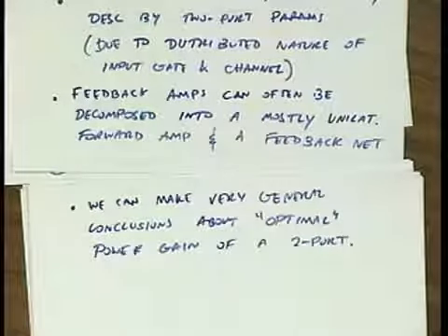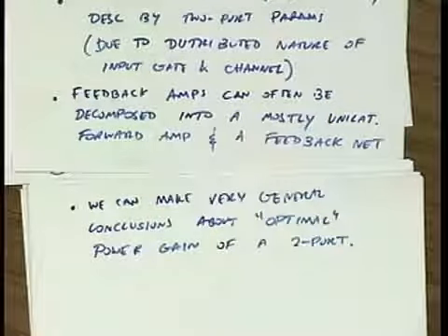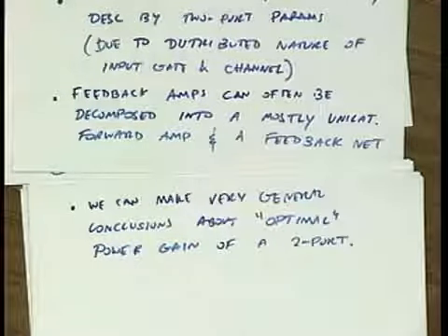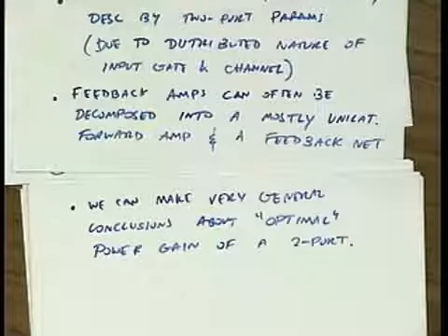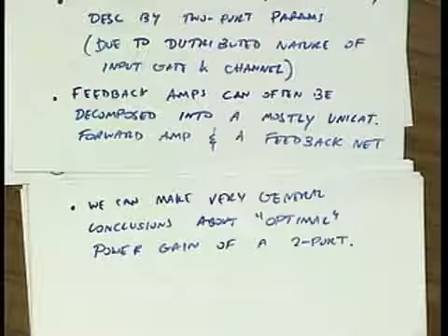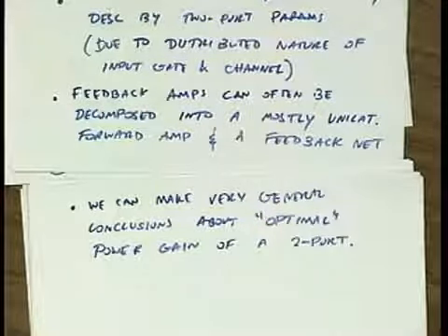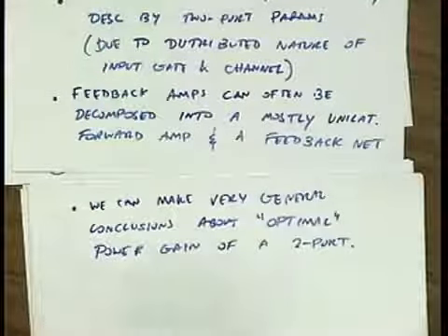And in fact, it turns out that when we go through these calculations, a lot of the metrics that we define for transistors, such as Ft, which you're familiar with, and Fmax, which is something that some of you are familiar with, really come from these kinds of detailed studies of the properties of 2-port networks. Fmax is known as the maximum frequency of oscillation for a transistor, or in general we'll see for a 2-port. Okay. Questions? Comments? All right.